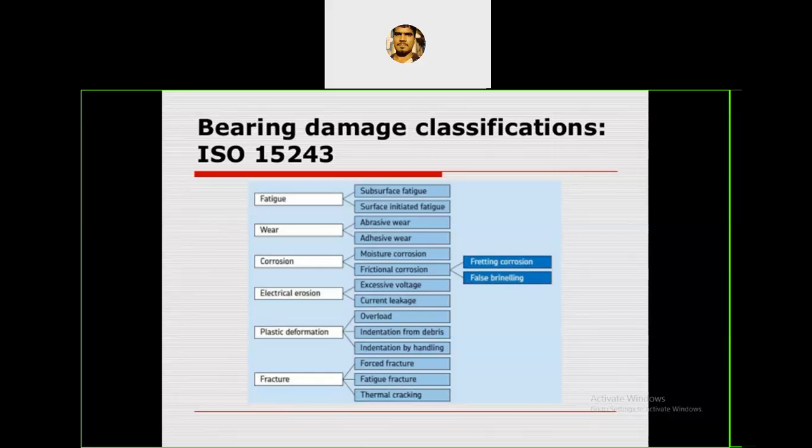That is erosion wear. The next type of wear is polishing wear. It is also a continuous and slow process, also because of the chemical action in the lubricant. Continuously, it removes material and leaves the surface very fine, smooth and shiny.